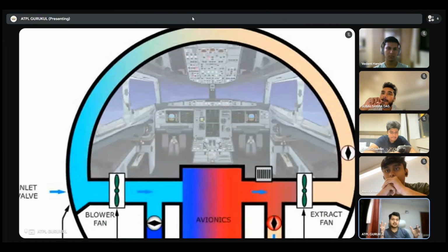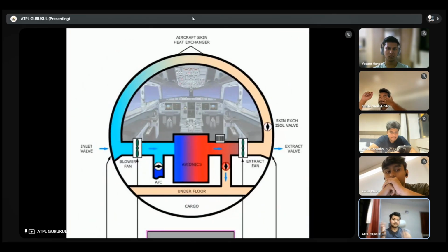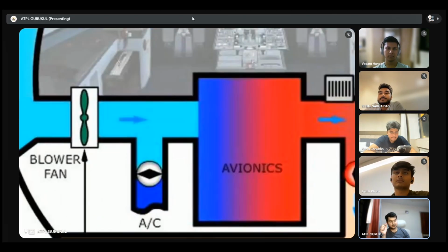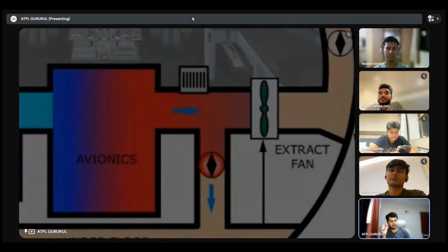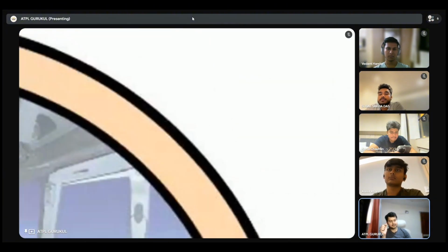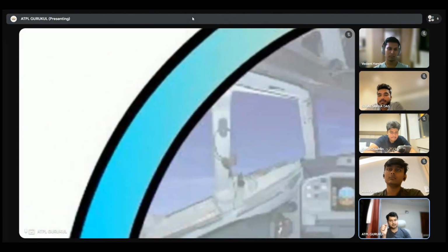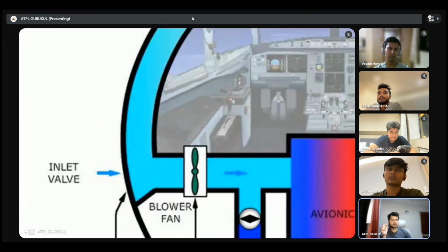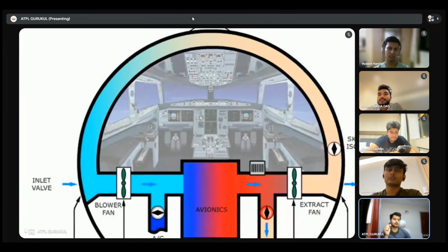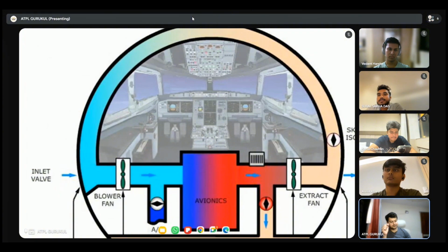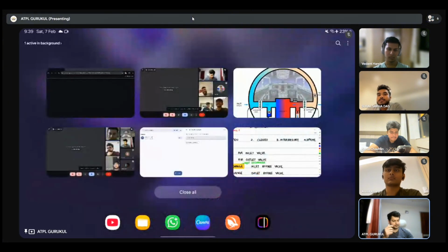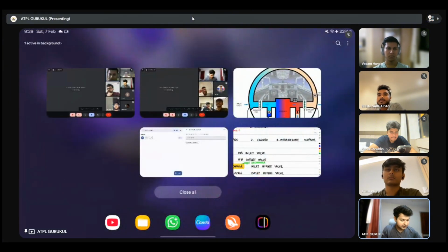ठीक है, एक आउटर स्किन है, एक इनर स्किन है, एंड उन दोनों के बीच से हवा जा रही है. So this is the cold air coming in from here. It is entering the avionics, getting hot, passing through the skin air heat exchanger, and it is becoming cold, and again going back into your avionics. Am I clear? This is the closed configuration. We will study these configurations in further detail in some time.